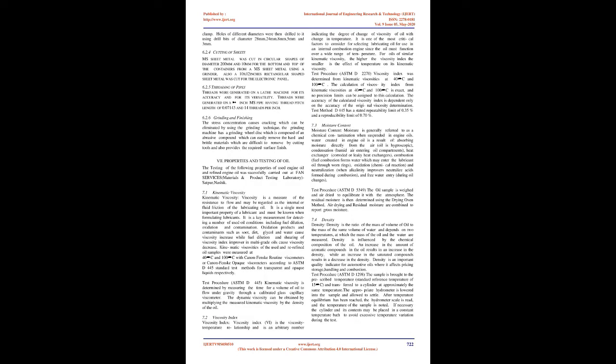6.2.3 Drilling holes for container. Holes of different diameters were drilled on the containers using the vertical drilling machine. The containers were placed on the regular work table and clamped to it using a G-clamp. Holes of different diameters were then drilled using drill bits of diameter 28 mm, 24 mm, 8 mm, 5 mm, and 3 mm.